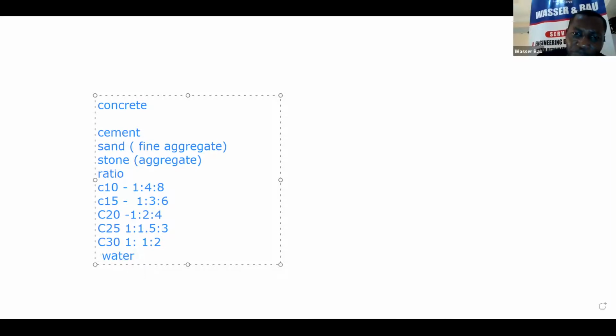That's why I tell people, when you see concrete that is very workable, fluidy, it does not mean it's the best concrete. Because the more water, the less the strength. The more water you put in concrete, the less the strength. The thicker, the less water, the stronger. But then, the concrete needs to be workable. Workable means you have to pass through formwork. It has to enable you to work it, sort of. So water cement ratio is very important.